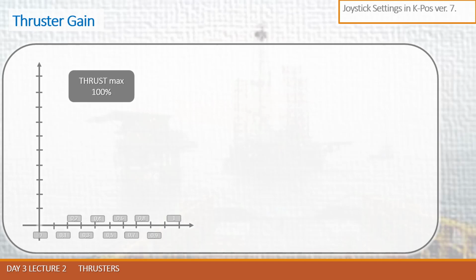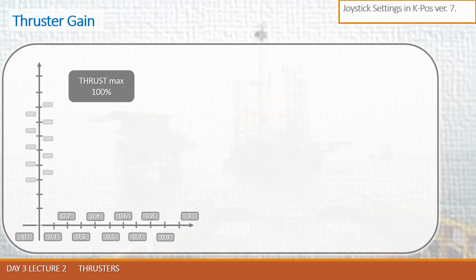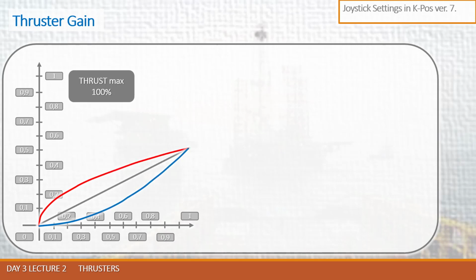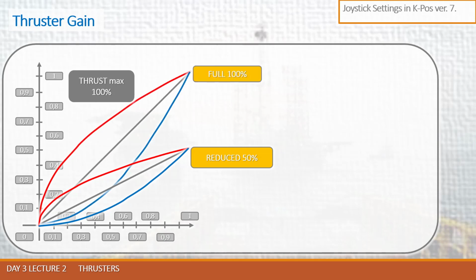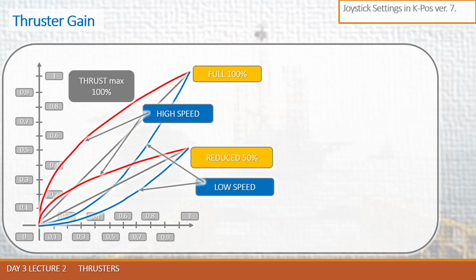Also there is a panel which is known as environment compensation. If you keep the tick there, then in joystick zero demand, the DP system will automatically compensate the environments on selected axes. So let's talk about joystick thrust.